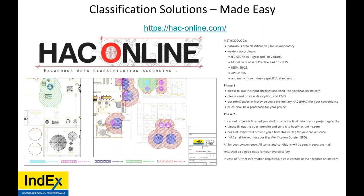Is EXD 2C equipment with hinge door acceptable in a zone 2? I don't think you're going to be able to find that 2C hinge door equipment unless it's only for hydrogen. So you need to take into account all the things that we've discussed and then apply that knowledge. If you need any more assistance, please feel free to contact us.